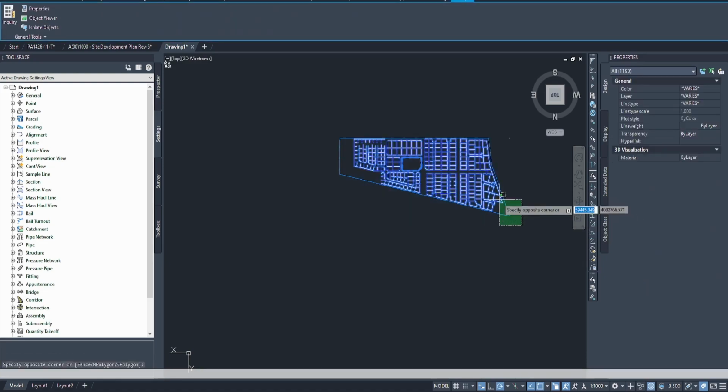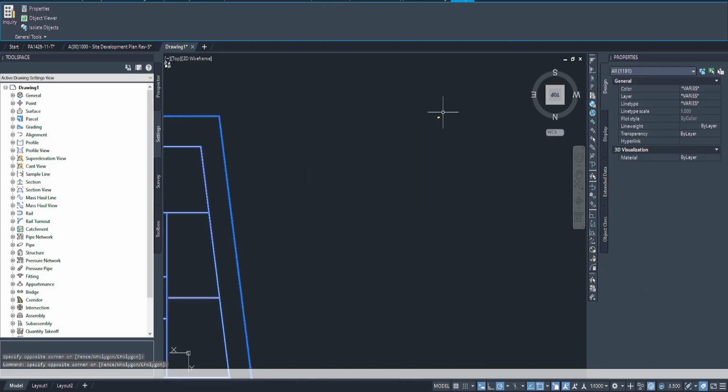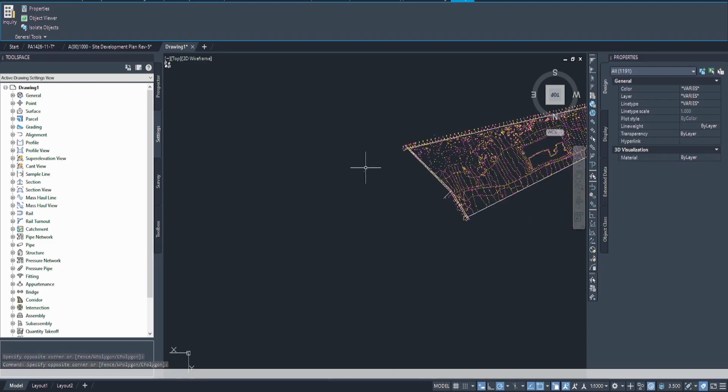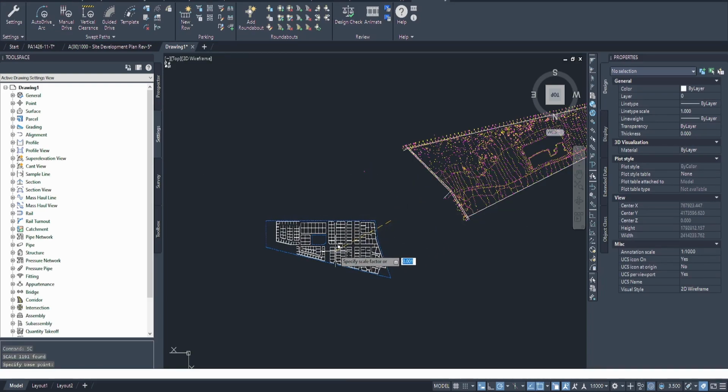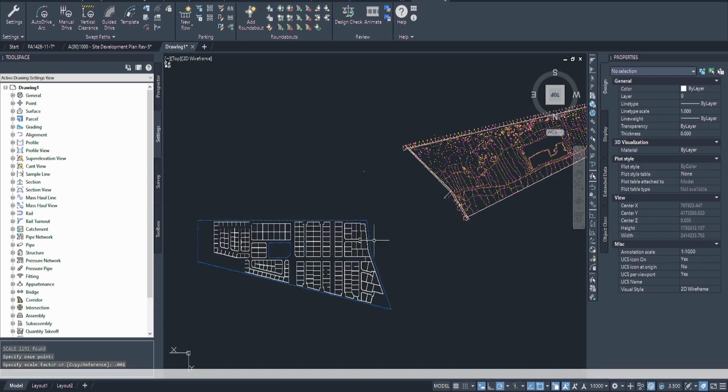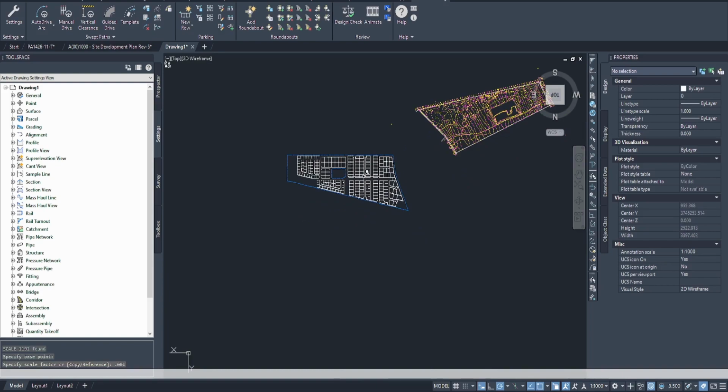drawing. I'll select all of that, zoom in a bit, and you can scale that. Just type SC and click anywhere, and there you go. If you scale to 0.001, that's 1,000 times smaller, so that corresponds with what we have.